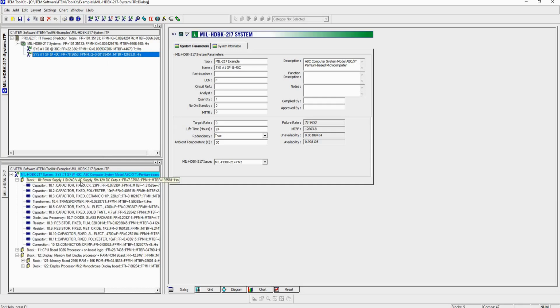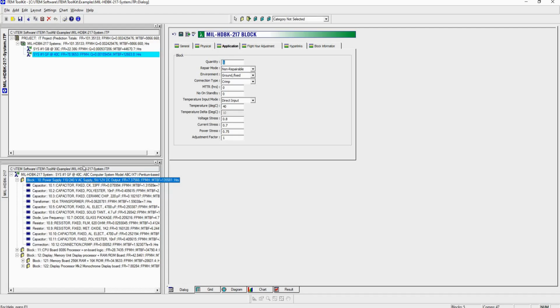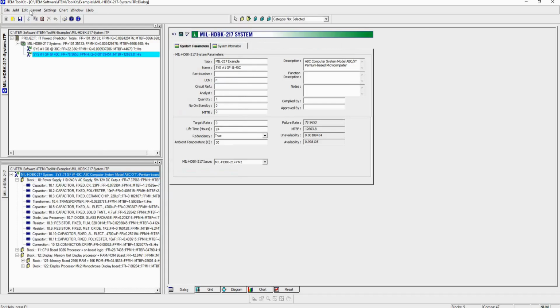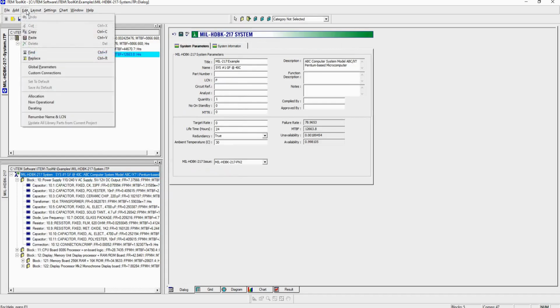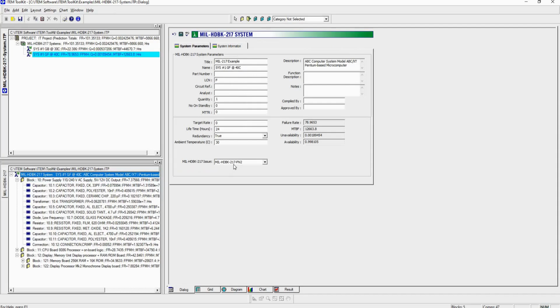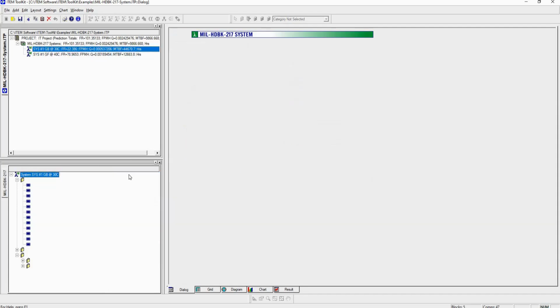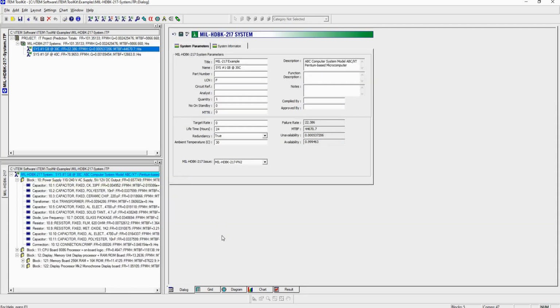This type of what-if analysis can be done for any of the parameters within the global parameters, and once you are happy with the changes and the new results obtained, you can choose to save the project or use the Save As option to give this a new project name. Now I will show you another way to obtain this type of what-if analysis using the chart option.